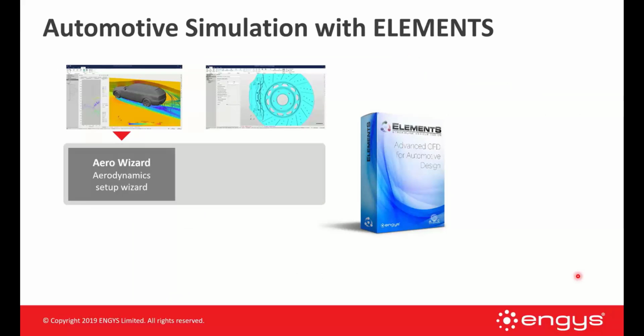There are several different components of Elements. The first and foremost is the Aero-Wizard. It's an aerodynamic setup wizard that automates a lot of the meshing best practices: what size of cell, how many layers, how do we mesh different components, the boundary conditions, what kind of boundary condition does a body panel receive versus what kind of boundary condition does a wheel receive. So a lot of this is automated within the Aero-Wizard.